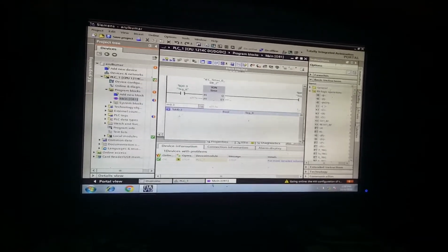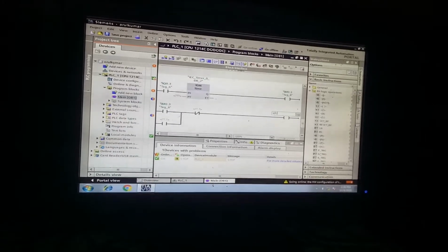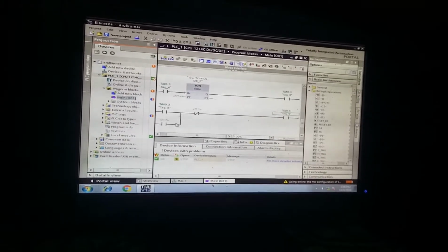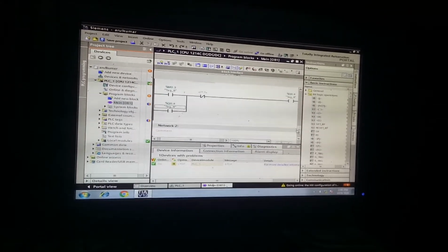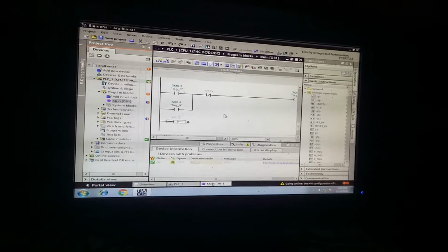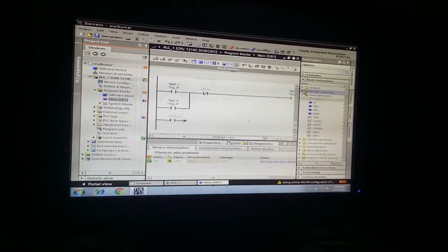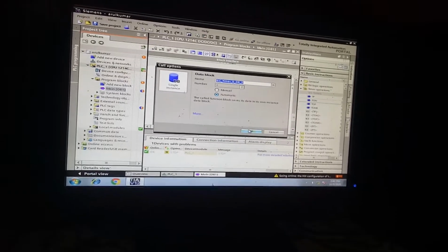M0.3 will produce an output as Q0.4, the final output. So that can be latched here, Q0.4. Then after that, the next timer. Though it's a continuous cycle of operation, you go for starting once again the first experiment, in the case of first run. So that's the reason I go for latching the last timer to the first run.